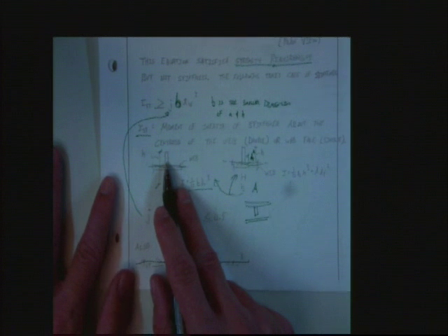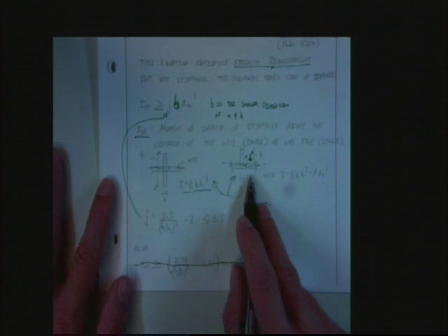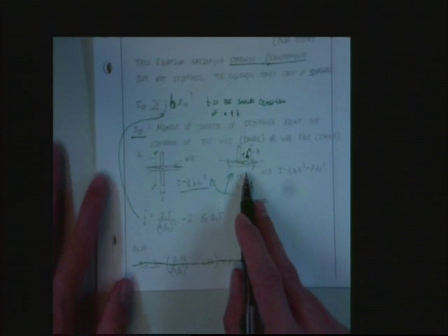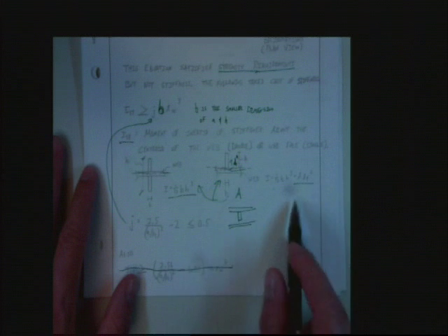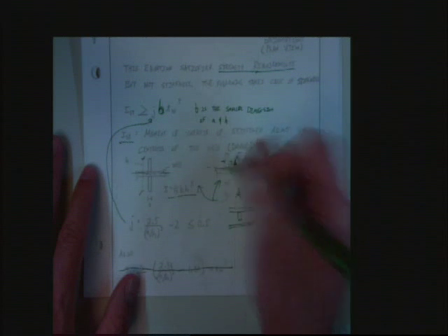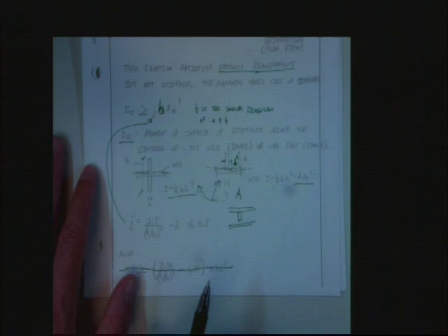Easy. And then if we have something like this, only a single-sided stiffener, it's the same thing. 1/12 BH cubed, but then we get an ADY squared term. Well, why? Because the centroid is off the center of the web.